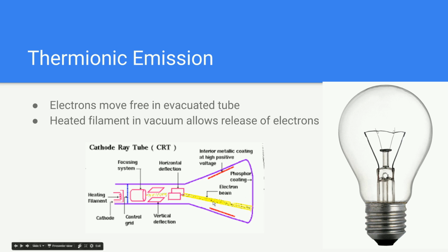When these electrons come and strike the front of the screen, which is coated with phosphor, it glows. And basically that's the rundown of how a black and white TV works: they come up, strike the phosphor, and create light. Then this beam just sweeps across the screen, drawing up the image. And then all the electrons that are left out here, they just get pulled up to the anode on the top and the bottom of the tube, and then are recycled through the whole system.